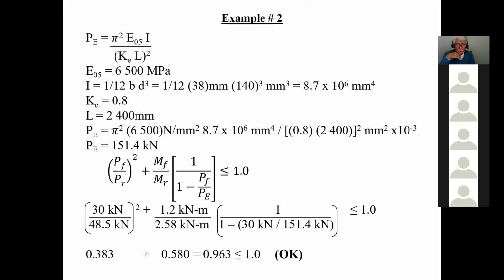Okay, so what I'm saying is that the further I am from 1, the safer the member is. The closer I am to 1, the more optimum my design is. In other words, the member cannot be any smaller than that. Okay, thank you. You understand? Yeah, I understand now. So in other words, if you chose a member and you get 0.8, I'd live with that. I wouldn't try to optimize it. But if I would get something like 0.5, I would try to see if I can optimize it. You see what I'm saying? At 0.8, I would live with that.